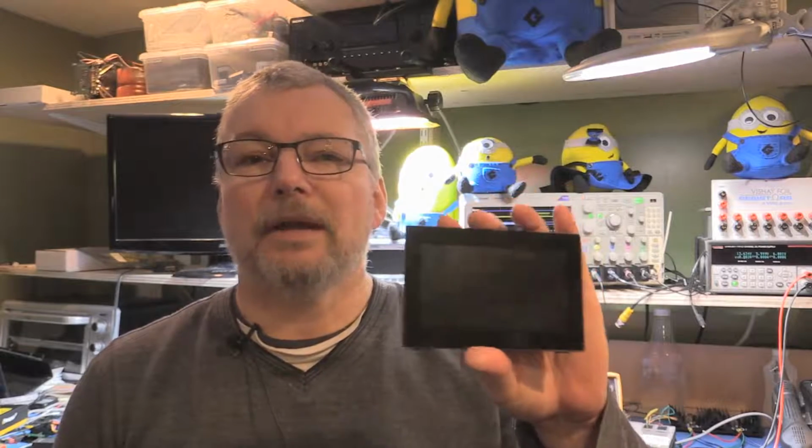Hi, a little while ago I did a video on tearing down a Lascar PanelPilotAce panel meter, where we had a look at what was inside and went through a few of the capabilities of it and what the limitations are for its input and output. One of the things that we knew about it is that it has a 4-channel 16-bit analog to digital converter with quite a wide dynamic range of input capabilities, including 4 to 20 milliamp loop, as well as up to plus or minus 40 volts.